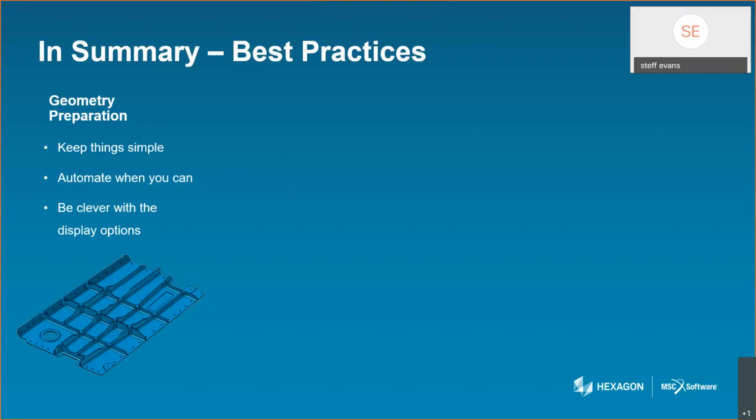And then thirdly, tip 3, be clever with your display options. So use auto color within the model browser, and use transparency to compare your 3D geometry with your underlying mid-surface and shell mesh definition.